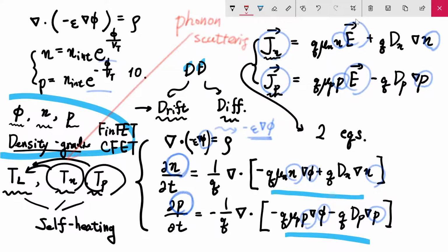Of course, if we have such a case, like even the lattice temperature is higher and carrier temperatures are lower, then what will happen? In this case, again by using these phonon scattering mechanisms, our lattice will try to heat up our carrier system. So always we want to have the same temperature because they are talking to each other. However, in many cases, the electric field, the energy stored in our potential energy, is first transferred to the carrier system, and after some time later, the characteristic time will be determined by the phonon scattering rate, and that will be related with this system.